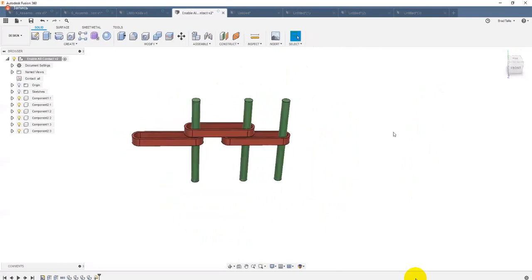For example, I helped a customer out. They designed the reclining seats in airplanes. And you can think of it almost like an S-curved garage door track, maybe. And so we simulated how much slop the wheels have in the track. And we could say drive joints when it's at 45 degrees, what angle is the footrest at, and all this kind of stuff. But we ended up using contact sets to do that.